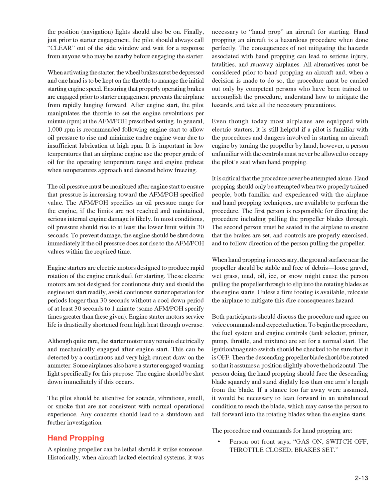Engine starters are electric motors designed to produce rapid rotation of the engine crankshaft for starting. These electric motors are not designed for continuous duty, and should the engine not start readily, avoid continuous starter operation for periods longer than 30 seconds without a cool-down period of at least 30 seconds to 1 minute. Some AFM/POH specify times greater than these given. Engine starter motor service life is drastically shortened from high heat through overuse.